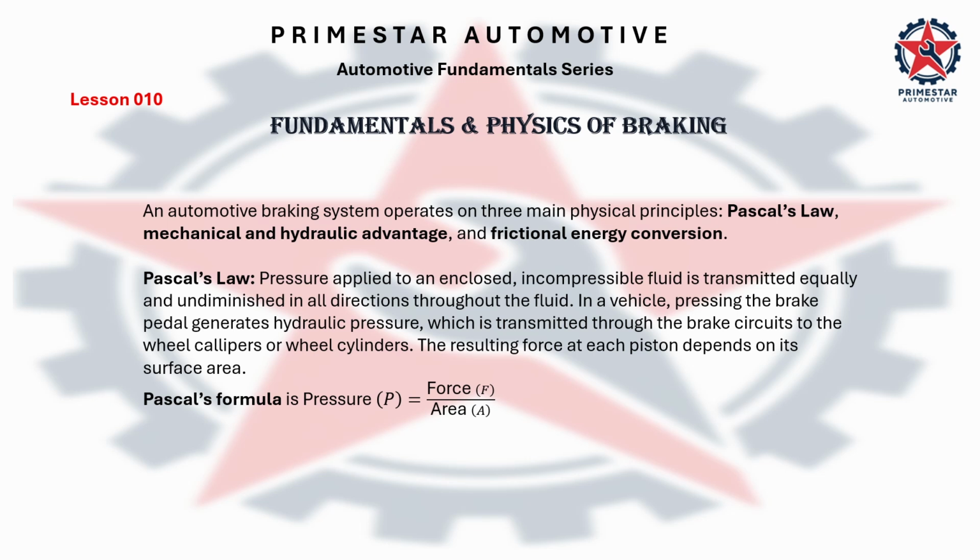In a vehicle, pressing the brake pedal generates hydraulic pressure, which is transmitted throughout the brake circuits to the wheel calipers or wheel cylinders. The resulting force at each piston depends on its surface area. Pascal's formula applied: pressure equals force over area.